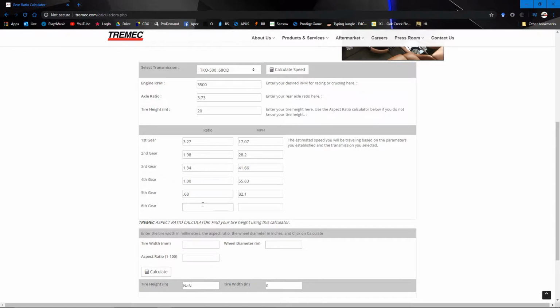I wonder if it's going to let me add another gear here. What if we did that? Put a, ooh, yeah, 0.5. And there we go. So then, if we had one more gear, a 6th gear, we could bring this down. Go back to 2200. Not quite enough to do 80. 2400. 76. 2600. There we go. 80 again. So we've lost almost 1000 RPM because we added another gear ratio here.